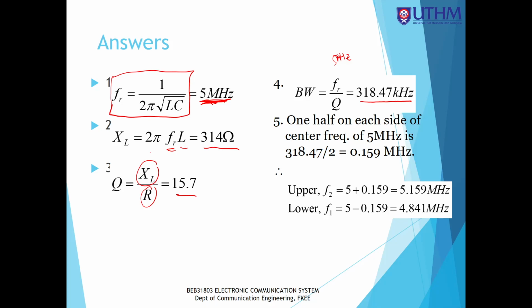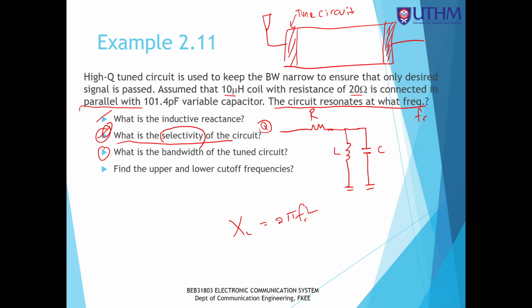Okay, so this is the bandwidth of the tuned circuit. From this picture, you see that the antenna is capable of receiving the whole AM bandwidth, including other frequencies as well. And the tuned circuit will limit the frequency band that we want to process in the receiver.